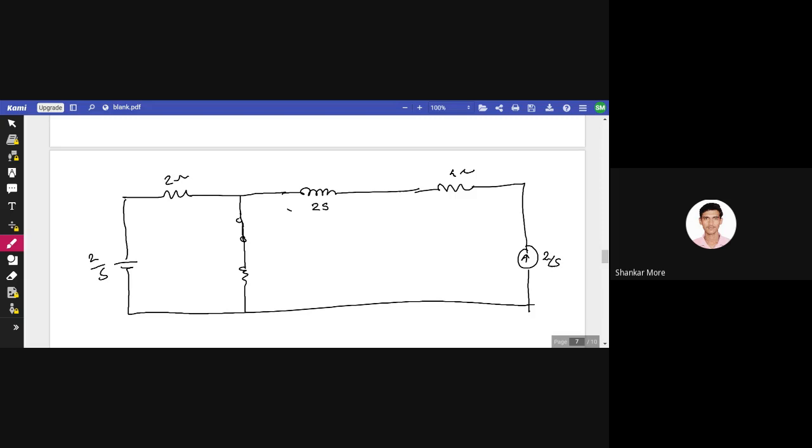सो देखो, यहां पे मैंने एक वोल्टेज सोर्स लगाया और हमारा जो कैपेसिटर था वो as it is ही है. यहाँ पे कैपेसिटर की वैल्यू क्या थी? It was 0.5 फैरड. ओके, सो 0.5 फैरड का अगर आप ऐसे लिखोगे, 1 बाय sC हम लिखते हैं ना, तो 1 बाय s तो as it is रहा, C is 0.5. सो 1 बाई 0.5 is 2 हो जाएगा, यानी कि 2 बाय एस हो जाएगा. तो कैपेसिटेंस की वैल्यू क्या लिखूंगा मैं यहाँ पे? 2 बाय एस. और ये जो वोल्टेज सोर्स है ये रहेगा 6 बाय एस.